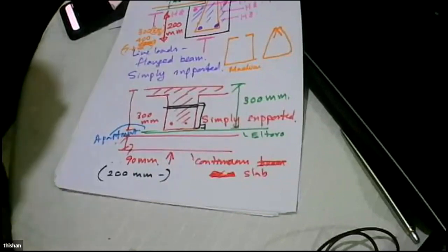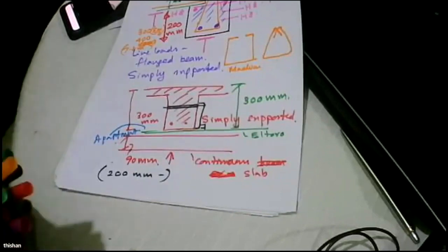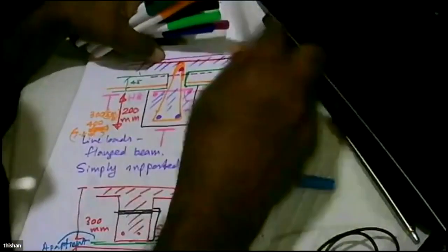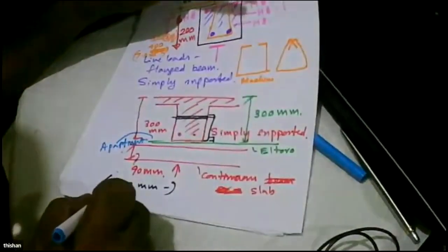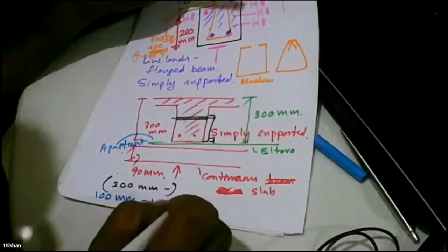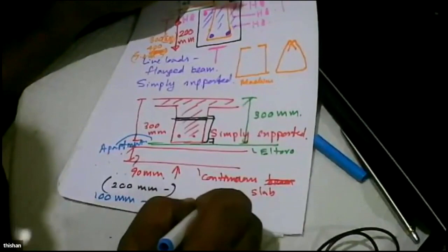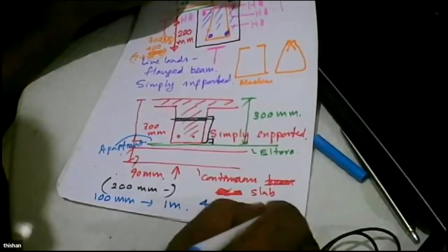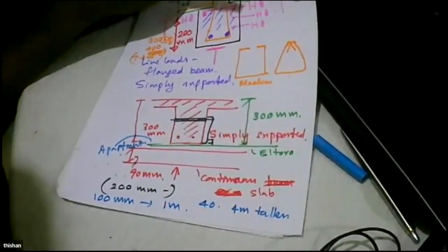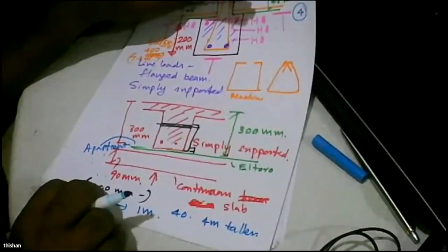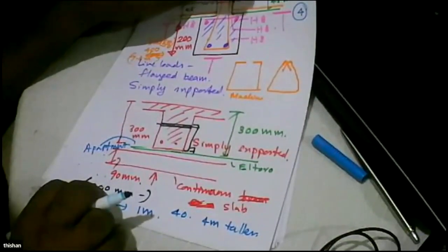Yes, sir. So what we do is, now we have a very practical solution, but there is a cost penalty of 400 millimeters per floor. So with 10 floors, your building will be 1 meter taller. With 40 stories, the building will be 4 meters taller. Not a major problem because it's only 1 floor taller, but we can make a significant saving in steel.